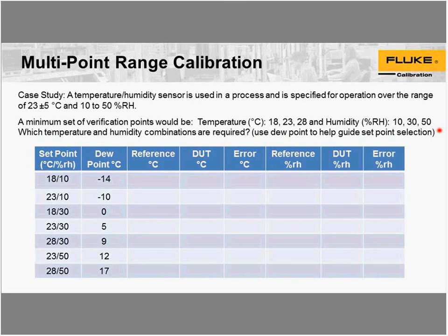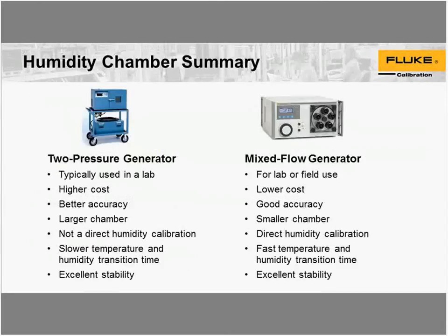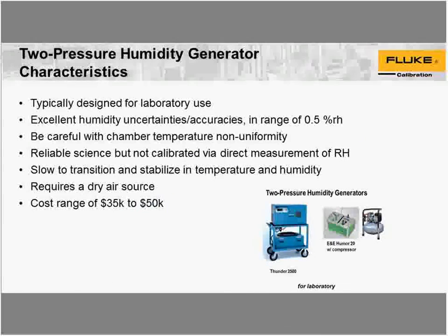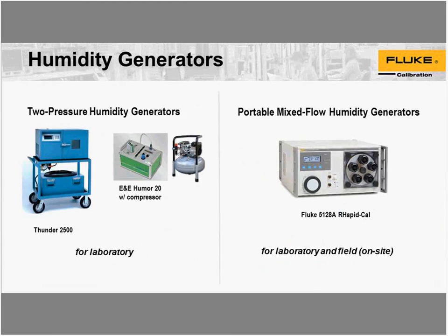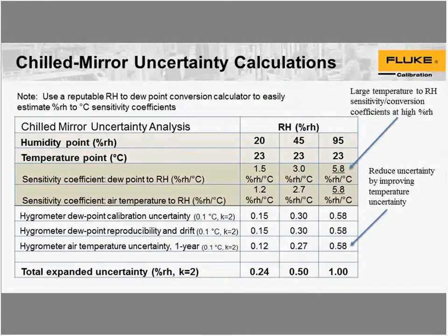If you back up to this slide, it gets a little tricky though. It's not as awesome as I originally thought when I looked at the separation of chilled mirrors from these humidity sensors. There isn't as much separation as I thought at the higher humidity. So to demonstrate that, we'll look at the slide. Certainly down at the lower humidities, like 20% and 45%,